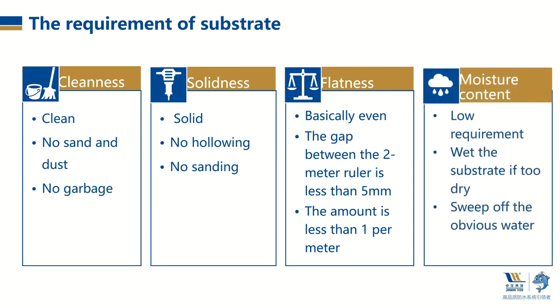Wet application is highly adaptable to the moisture content of the substrate. It can be applied on a wet substrate, and if it is too dry, wet it in advance. After rain, sweep off the obvious water.